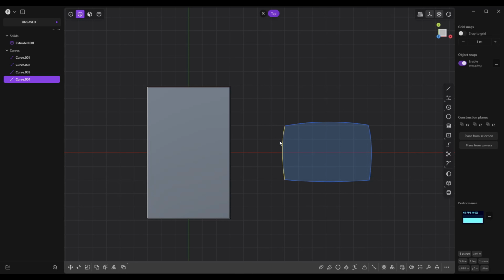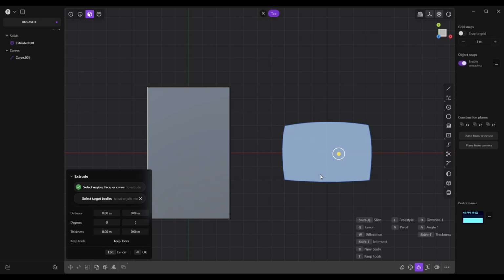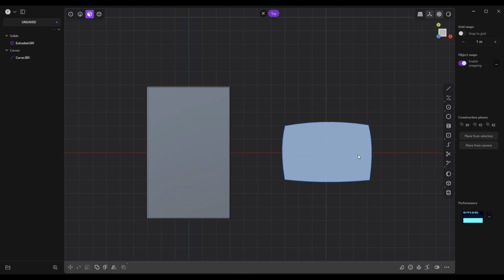And there you go. Now we want to combine these, so we're going to make sure we're in edge mode. We're going to drag select all of them. We're going to press J on the keyboard, and as you can see, they're now all combined. And then we're going to go to object mode. Actually, it's not an object yet. We're going to go to face mode. We're going to hit G to move it, not extrude.